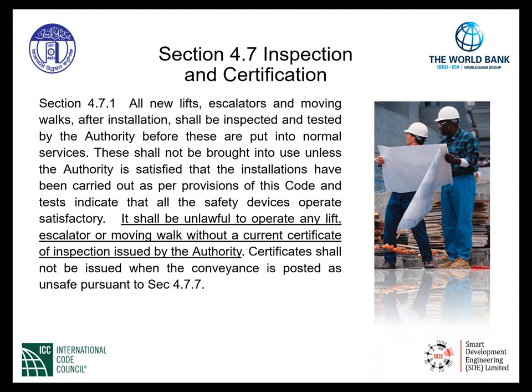installation. It shall be unlawful to operate any lift, escalator, or moving walk without a current certificate of inspection issued by the authority. Certificates shall not be issued when the conveyance is posted as unsafe pursuant to Section 4.7.7. This section carries out the requirements and the certificate of inspection that must be issued by the authority. When the certificate is issued, all of the safety inspections have been completed and verified that the lifts and escalators and moving walks are safe now for the occupants of the building to utilize accordingly.